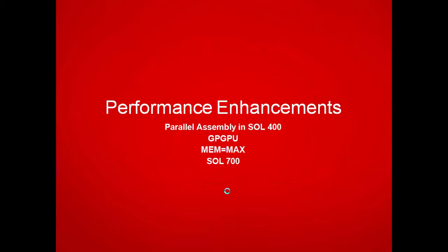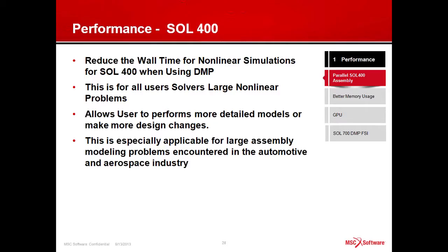Performance. Performance is always important. In MSC Nastran 2013, we have a variety of performance enhancements. The first one I want to talk about is in SOL 400. SOL 400 is, of course, the nonlinear solution sequence for implicit analysis in MSC Nastran. When we do a nonlinear analysis, as opposed to traditional linear analysis, usually the solution time is dominated by forming the stiffness matrices. So this is an effort to reduce the time associated with these stiffness matrices in reasonably large